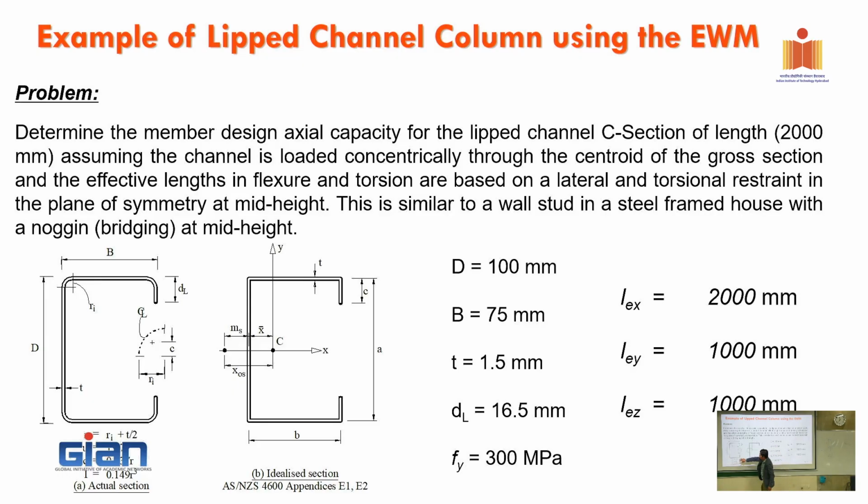All right, so this is a practical section. When you calculate the shear center and centroid by hand, that is challenging, right? You can do it by using ThinWall that I sent to you. It's very simple. You put that one in, click the button, and the program will tell you where the shear center or the centroid is. But you're not always going to have ThinWall 2 or the similar one, CUFSM from the US. Then how are you going to do it?